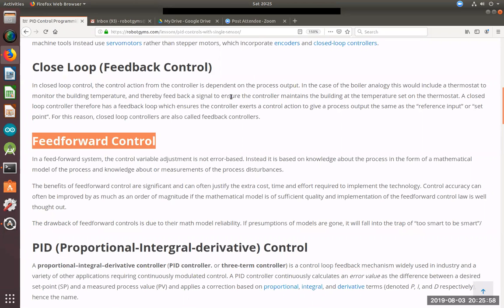You should automatically slow down and disobey the proportional command. For example, if you do proportional totally, that means say your 90 degree you map to 1.0 power, full power 1.0. Your 45 degree will map into half throttle, 0.5, right? Right? So that means when you're turning at 45 degree, you're still accelerating, right? So that means 45 degrees is still overshoot.